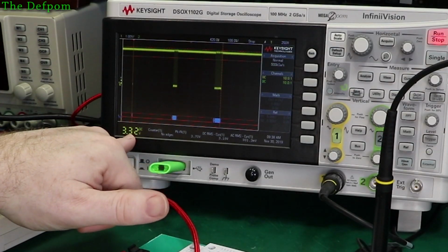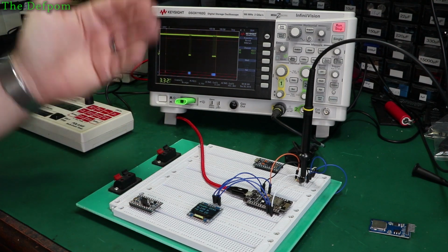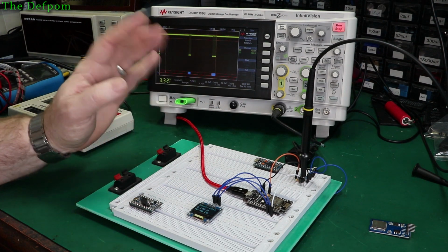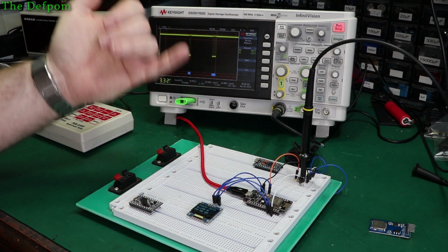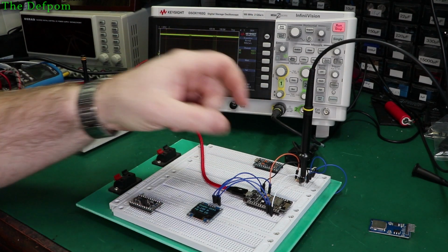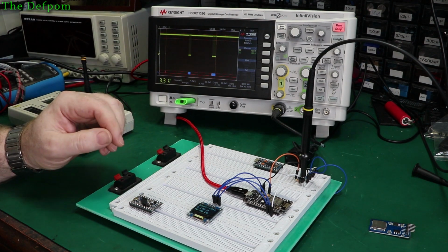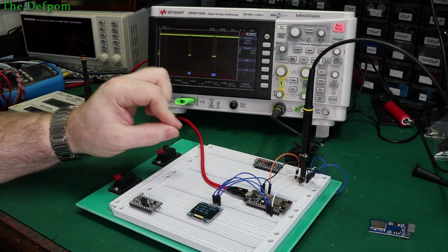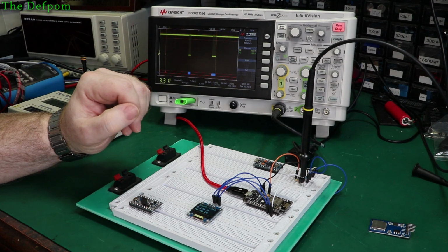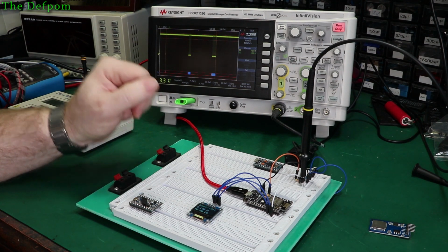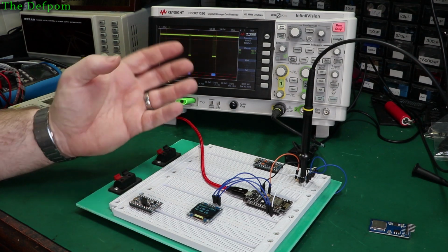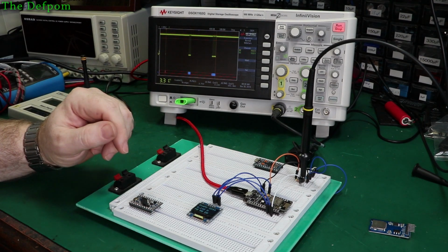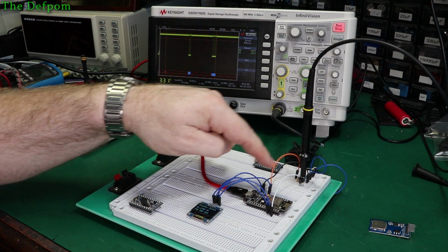So it says 3.3 here. That's what I was measuring, 3.3 volts, because it's in its high state. So it'll be pulling down to ground, it won't be going below ground. Mind you, I'm shunting across with a transistor, so maybe it will be producing something slightly lower. There is inductance in the cables and in that small section there. Inductance was what caused it to work, so let me try and string a train of thought together. A buck converter or a boost converter uses inductance to affect the voltages, okay? So in the boost converter, for example, it will shunt across the inductor, which causes a current spike, and then when it unshorts, it boosts it up, it causes a voltage increase. And you can get a similar effect when you're switching across the supply with a transistor.